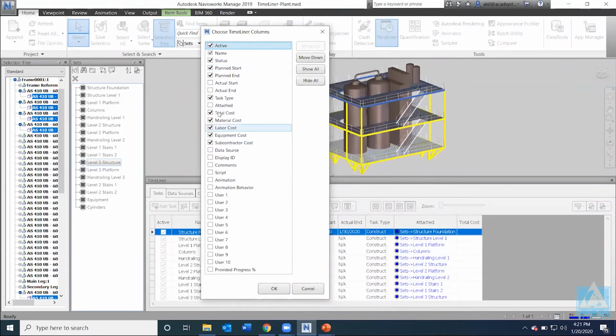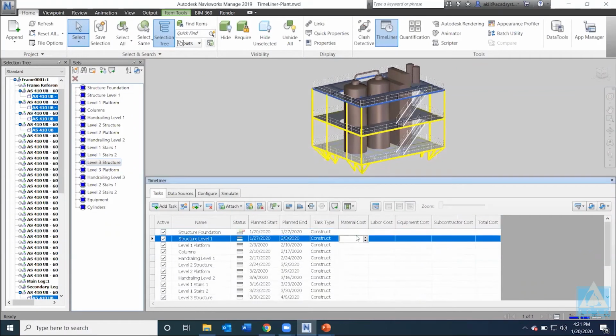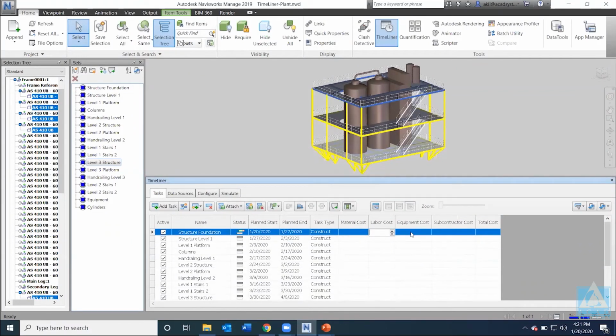And with this costing data that you're going to put in, you can sort it based on the column position. For instance, if you want the total cost to be at the end of the column, you can click move down, okay, and then if I click OK, all those columns for material cost, labor cost, equipment cost, subcon cost, and total cost will be listed in this work program.